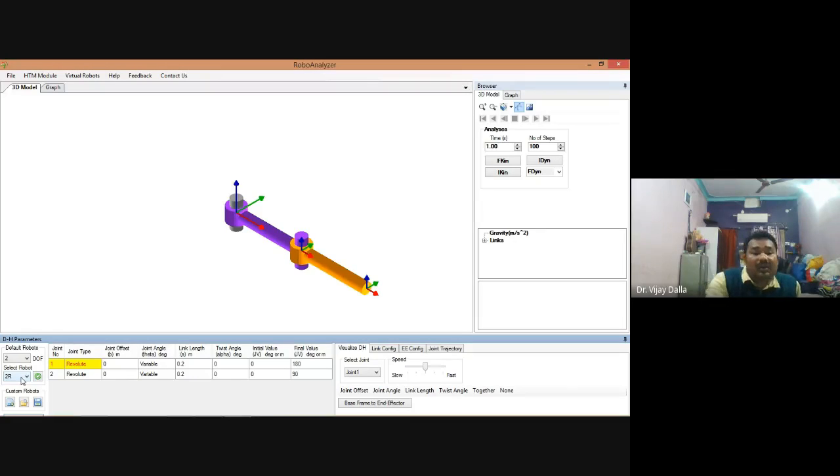If you want to know the positions and the orientation of the robot, for this simple robot we can easily get them. How? Suppose for the x tip, you want to write the tip position equation. X is equal to L1 cos theta 1 plus L2 cos of theta 1 plus theta 2.